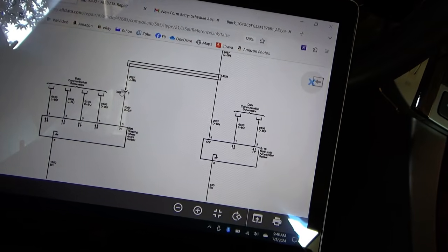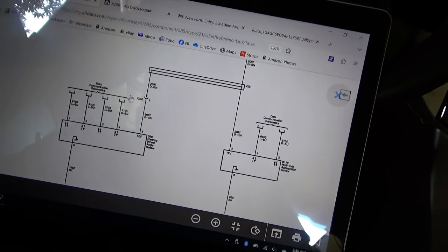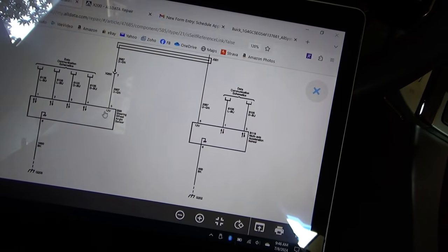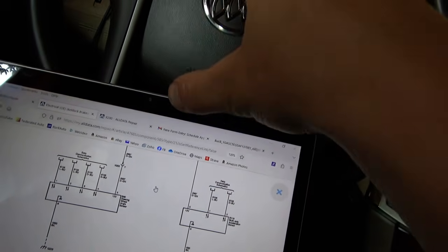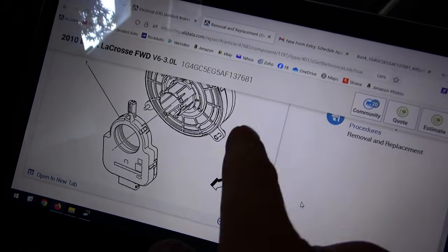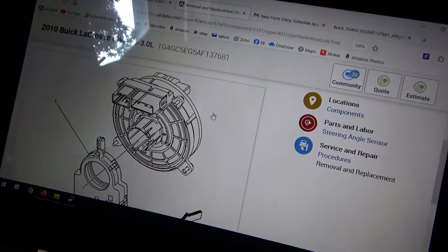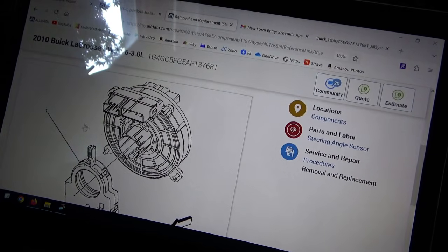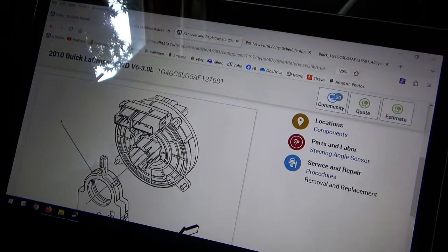Well, you can see this one, there's an X200 pin 7. Maybe we can disconnect that to get the steering wheel angle sensor out of the way, or I can look up how to get to it. Maybe it's not too hard to pull this cover off and just unplug it. Alright, so here's the steering wheel angle sensor, and it piggybacks off of the airbag coil spring, the what do you call this thing? Right behind the steering wheel, clock spring.